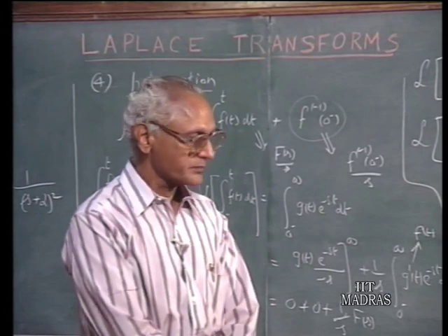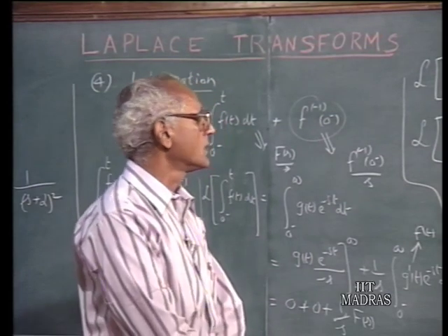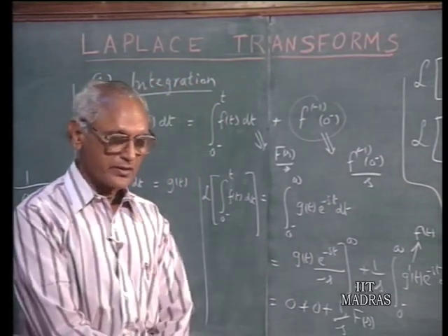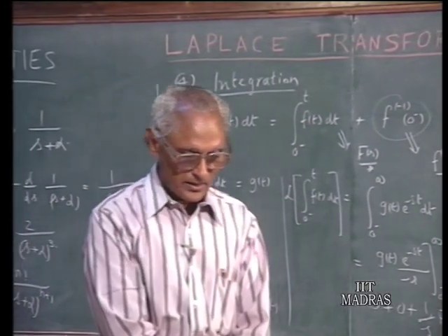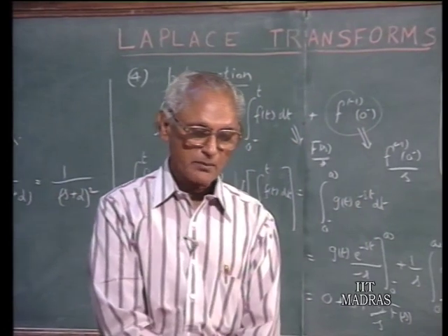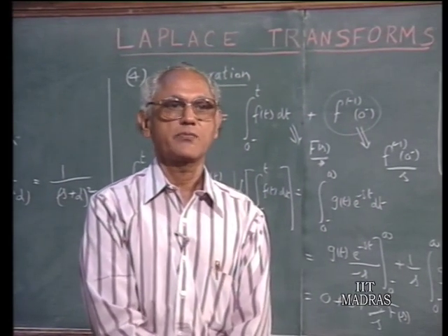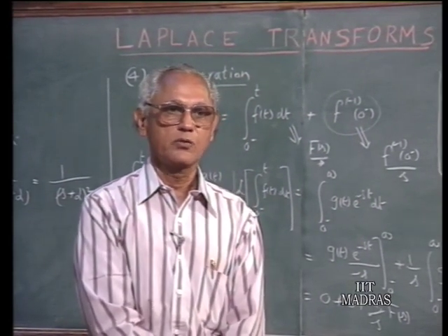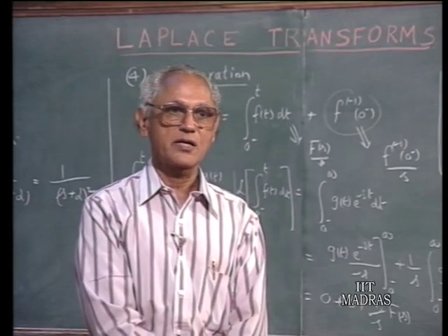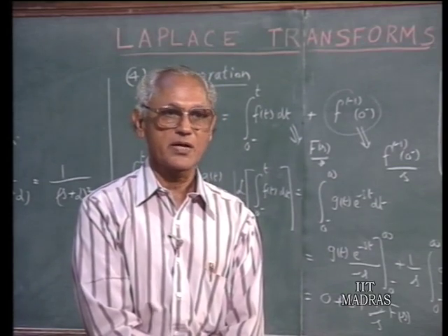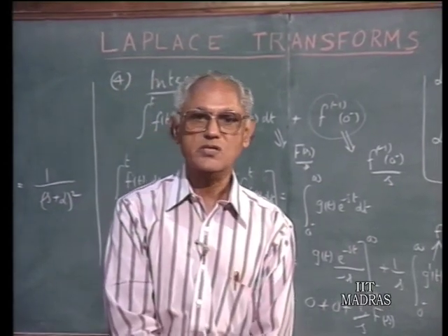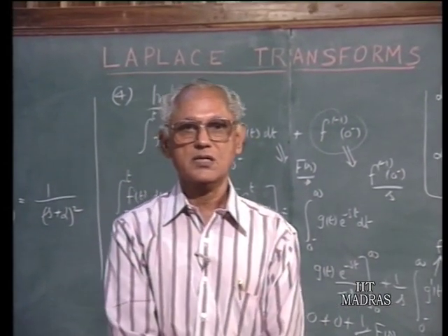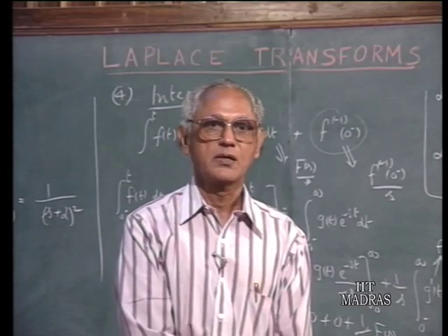Then we went to the integration of time functions, and we distinguished between the definite integral and the indefinite integral, and in both the derivative case and the integral case we saw how they can be applied to the situation of an inductor and a capacitor, how the relation between the transformed variables of currents and voltages across inductors and capacitors can be represented by means of certain diagrams which we called transform diagrams. We will continue the discussion of the properties of Laplace transforms in the next lecture.